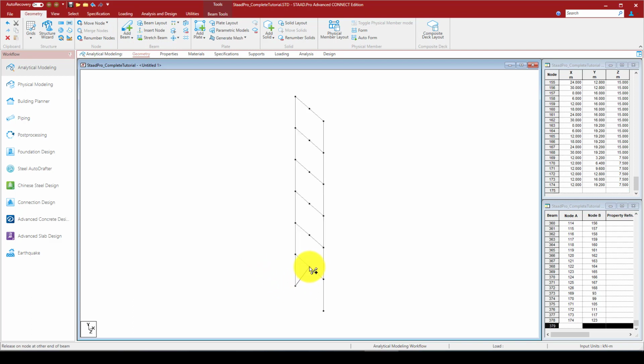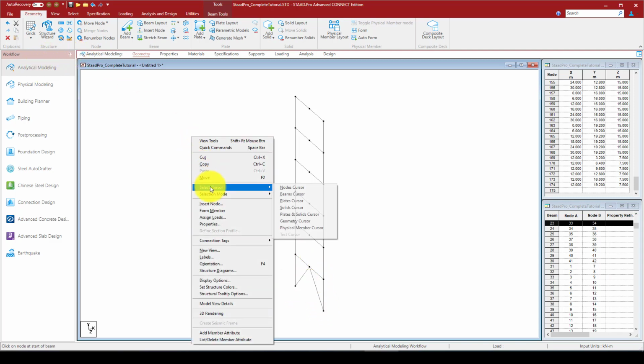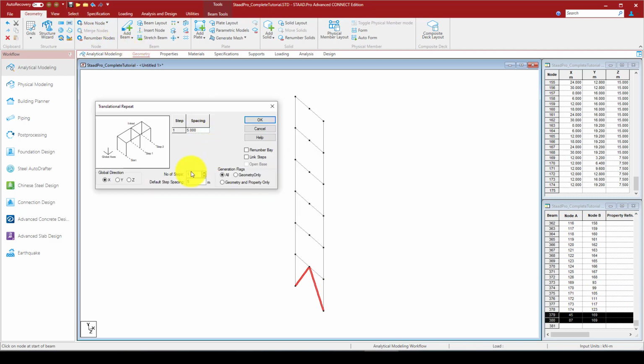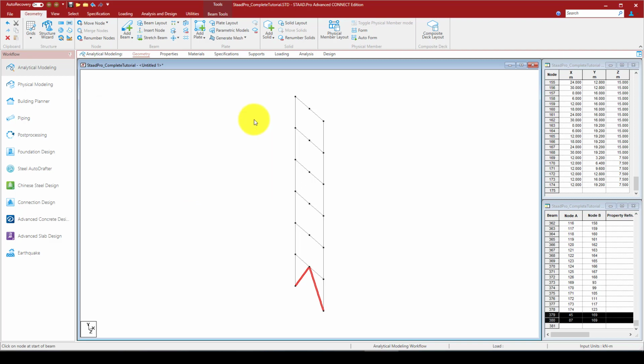So now I can select the beam and add bracing here to here. Now I can select with the beam cursor and select these 2 beams. Now I use this command, called duplicate. Let me use 5 in the Y direction, for the top stories, and each story is 3.2 meters. And you can see the entire process modeled in one direction.